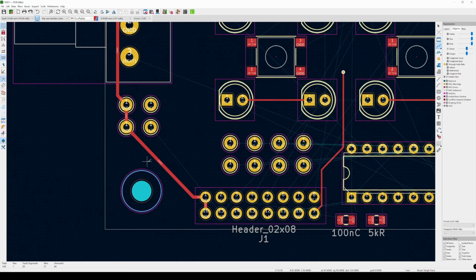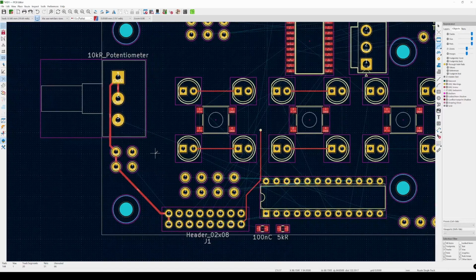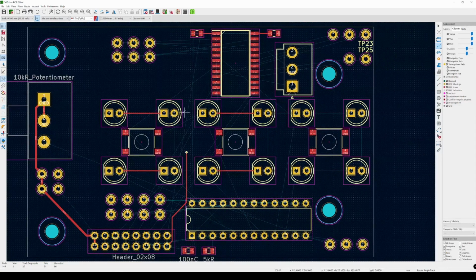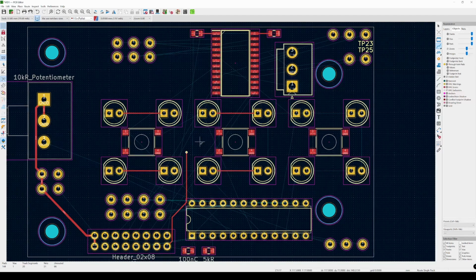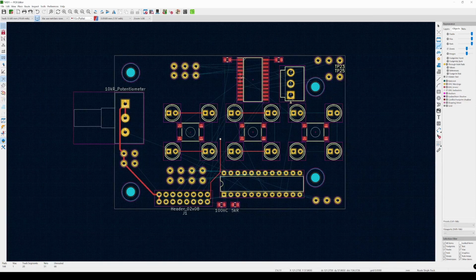but at some point you will have a lot of wires going all around, and you will need to start to adjust already existing places. You need to add a lot of wires, so go to the bottom layer, back to top layer. Try to keep the wires as short as possible, so it's just the simplest route that you can take, or you should try to make the shortest route that you can. But sometimes you might need to go a little detour around the board, and that's okay. Just, if possible, try to find the best way.